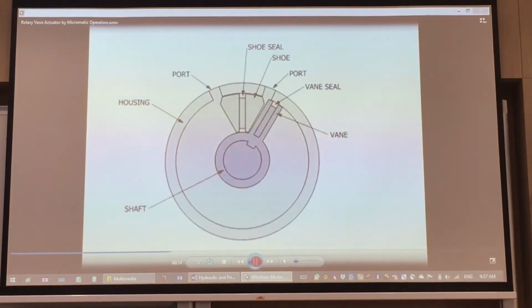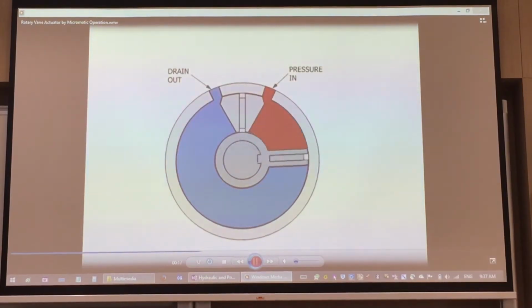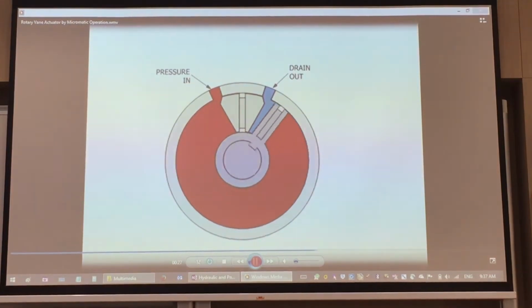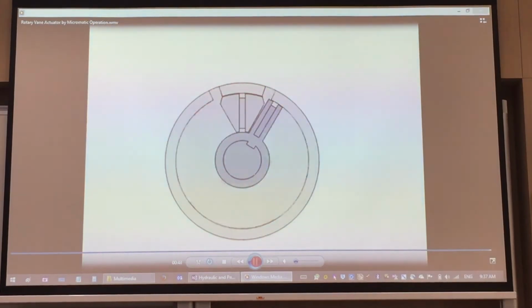I want that continuous rotation that the motor would offer, because it's hydraulic, it's going to give me a lot more power. Yes, there are other mechanisms that can do that, but in your lecture material, it's actually not covered. So we only look at this case where this pushing is being done. There's another type that I was using, which has a lot of pistons in between, and then you can rotate continuously using hydraulic fluid. Those are called hydraulic piston motors.